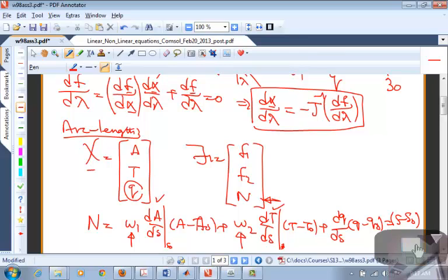So if I'm having this equation with W1 equal to 1, W2 equal to 1, the definition for the arc length is going to be dominated by temperature, not A naught. Okay. So what I need to do is boost this number up. So I'm going to put a weighting factor of 10 or something, and I'm going to scale this down. Okay. So I'm going to maybe put a scaling factor of 0.01. Okay. And this is something that I choose.